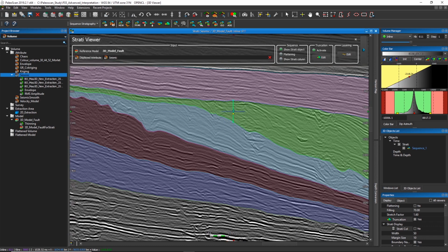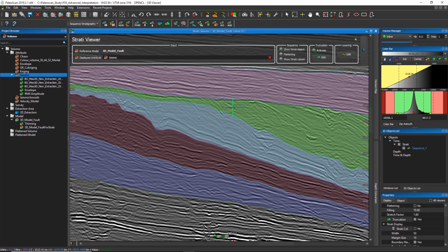And actually the thickness of the layer where I put the cursor is also defined as a thickness threshold. So all the areas with the thickness lower than this threshold will start to be changed. Here you can see I put the cursor at the location I want the truncation to begin. And then I will have two options for the truncation direction.